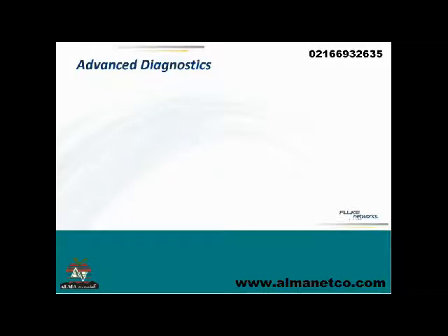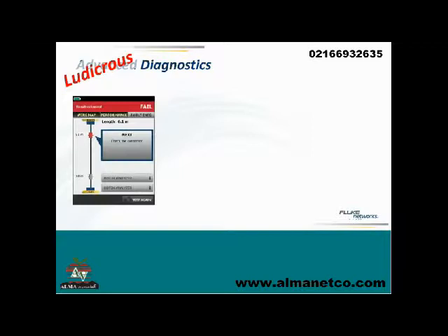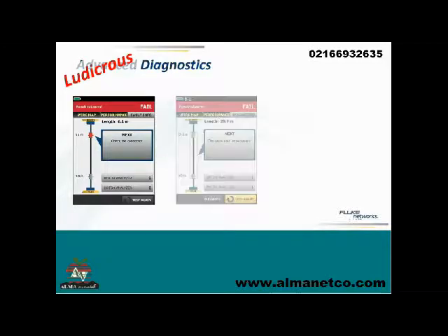Our DSX series has what I like to call ludicrous diagnostics. Yes, of course it'll find opens and shorts and split pairs and which cable goes where and all that, but it can find some really detailed stuff that I don't even know how it finds. So it can not only tell you, say with a crosstalk problem, that there's crosstalk, it can tell you which connector the crosstalk is in. So if somebody untwisted a little bit too much, we know which connector it's in.